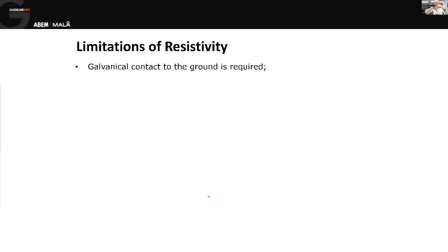We place that on the bedrock and normally put some kind of conductive material, either clay or gel, between the plate and the bedrock. And what are we doing there? Well, we're increasing the surface area, which makes it easier for the current to pass between that plate and the geology.